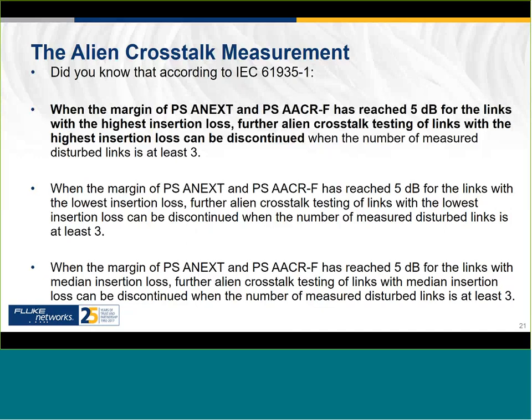Now remember, just because the solution is shielded, that does not mean you do not have to perform alien crosstalk testing. You do have to perform alien crosstalk testing for shielded and unshielded Category 6A solutions or Class EA, and for all Category 8 solutions, which are shielded solutions. We need to know that the shields are working correctly.